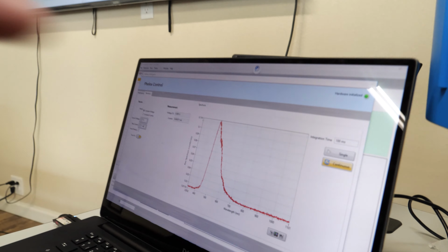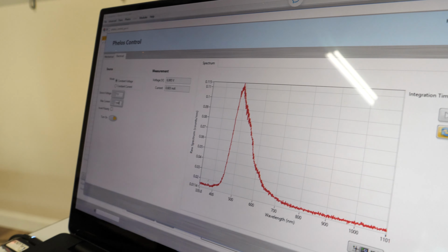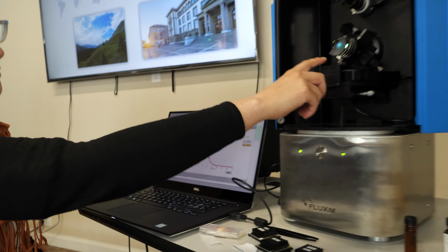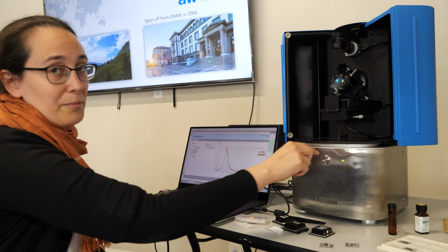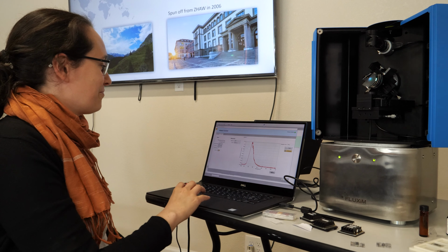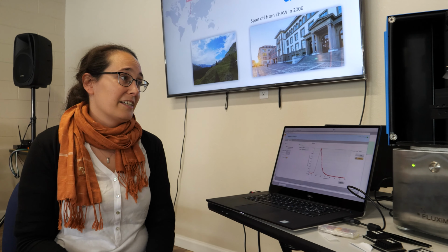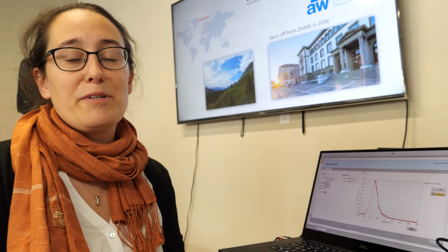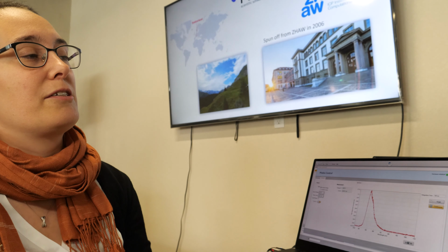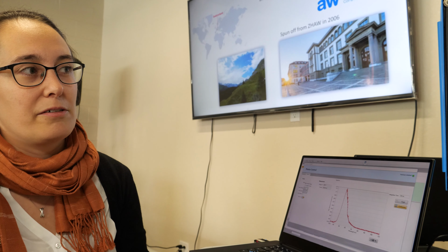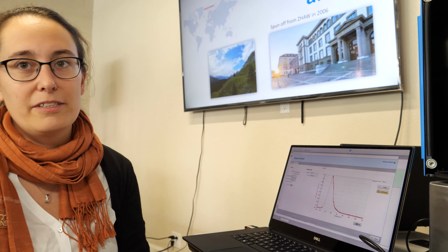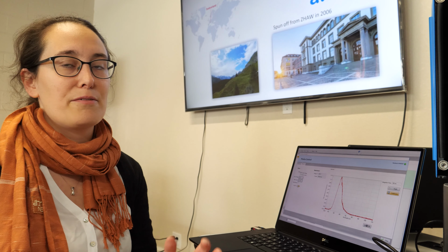What is this curve here? This is the spectrum live recorded that is going through this from the OLED through the fiber into the instrument. Is that a really special instrument for the whole industry? Yeah, it's really necessary to characterize your emitter film, especially this is suited for OLED pixels, so you can analyze the dipole orientation, emission zone, and many more things.